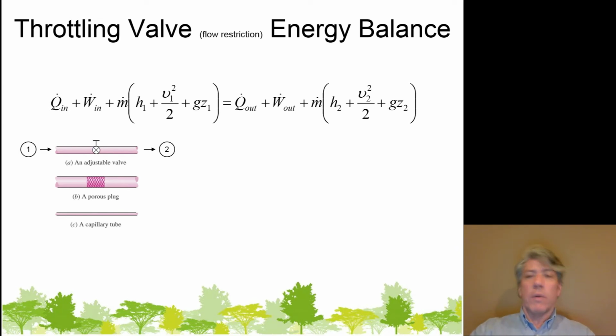And you might say, well, wait a second, what's going on? How can the temperature drop? I'll show you in just a second. Stay with me. What about the work term? Well, again, inside of a throttling valve, there's usually not moving parts. There's not pistons and things that are moving. Even if there is in a thermostatic expansion valve, it usually moves and then stays essentially within a range. It doesn't contribute a significant work amount. So most of the time the work terms are also crossed off.